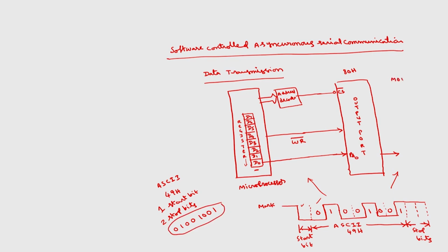First I will take MOV AL, 80H, because this 80H will be the control word for making all the ports output ports in mode 0. Because this is also 80H, to avoid the confusion, I will take this as F0H. F0H is the port address of port A. Then F3H will be the control word register. So, OUT F3H, AL. So, this will program all the ports as output ports, but of course, we are using only one port.